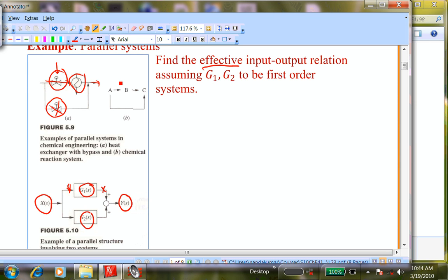And over that high flow regime, you may want to control it. So the control action will be on this valve. And then when you want to switch to a low flow regime, then you would have a bypass opened at a certain level, but still the finer control will always occur through this.